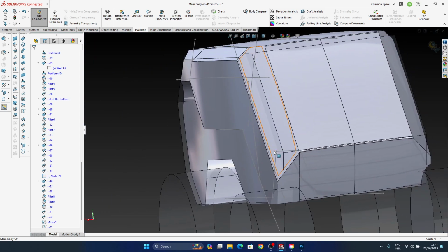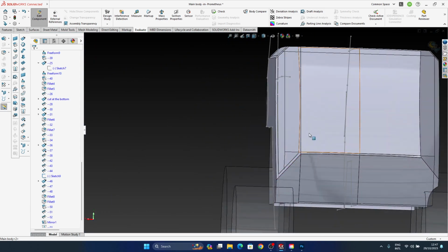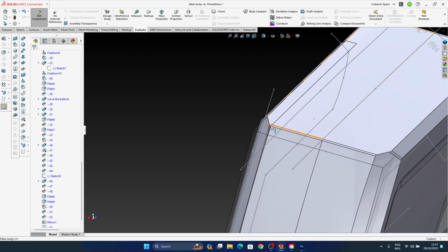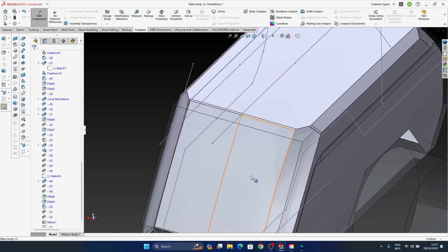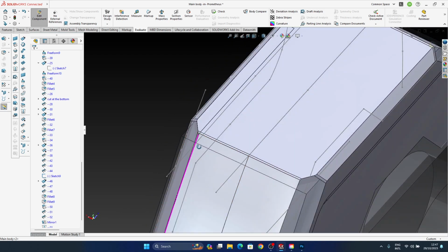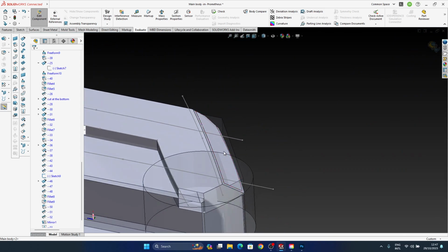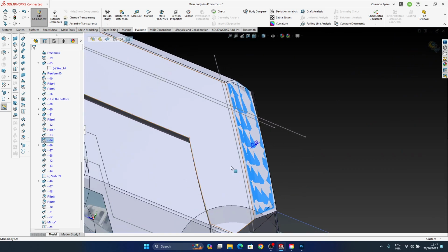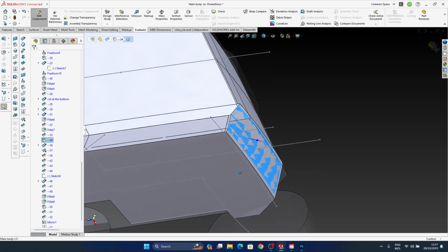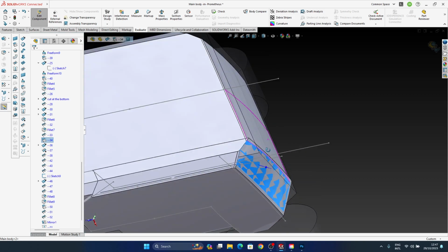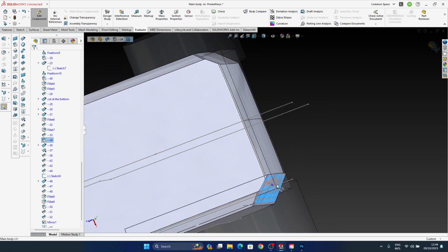And before starting to cut these with other surfaces and force SolidWorks to accept whatever we did, I'm thinking that here at the back, I don't like the fact that this surface offset, I want to have a bigger offset.